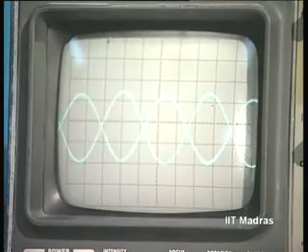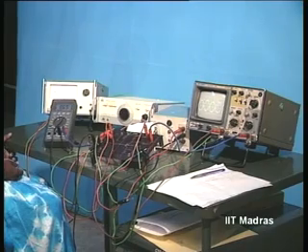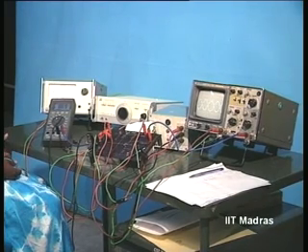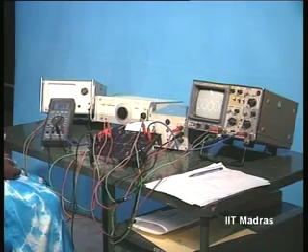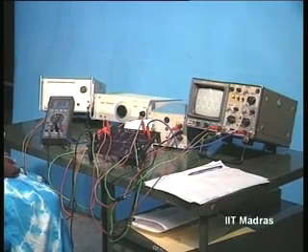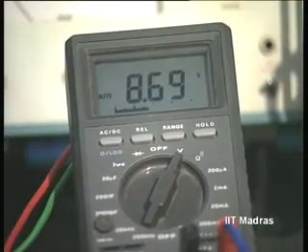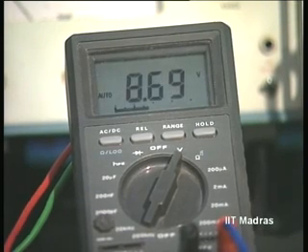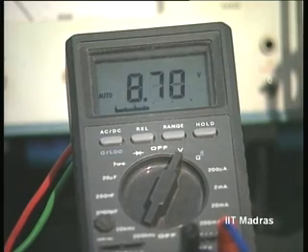Now let us increase the signal. You will see that there is very little distortion because the input voltage has dropped across the 2.2 K instead of across the transistor, which is a nonlinear device, and this has become almost linear. So the DC voltages remain the same. Now we don't have to bother about the DC voltage, that remains unaltered, there is no distortion.